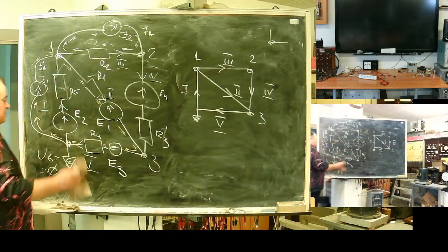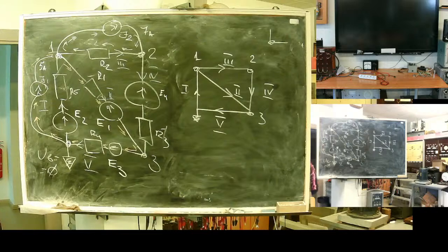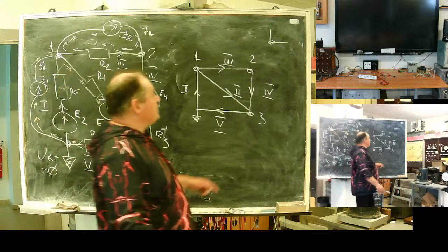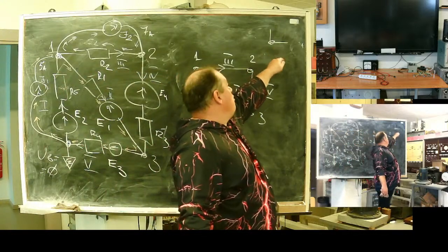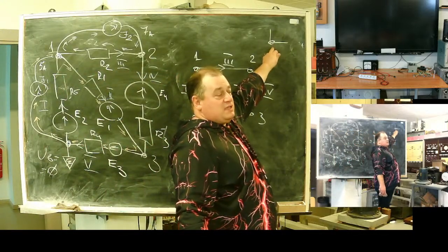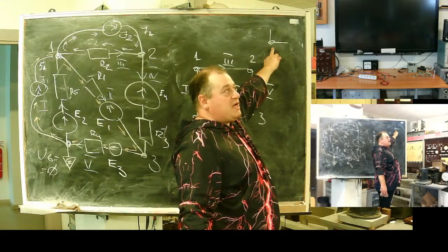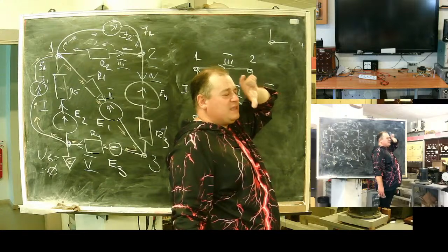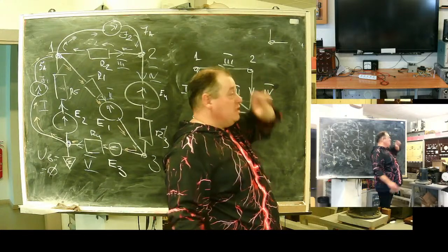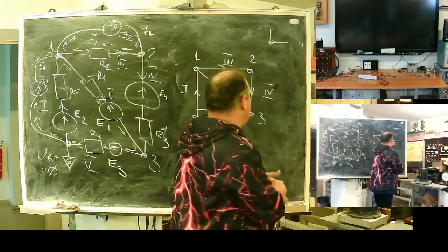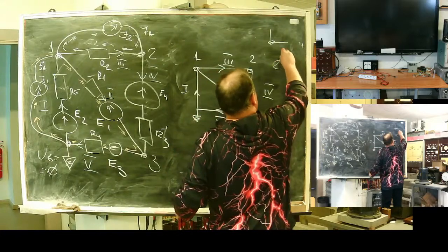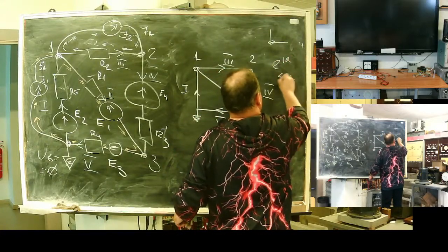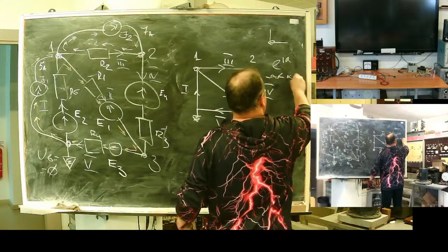Okay, it's possible, but it's a kind of hell, because voltages will be a problem. If we have a disconnected part, voltages in the island will be correct by magnitude, but they can take any angle. The solution for this part will be multiplied by e to the power j alpha, where alpha is from minus infinity to infinity.